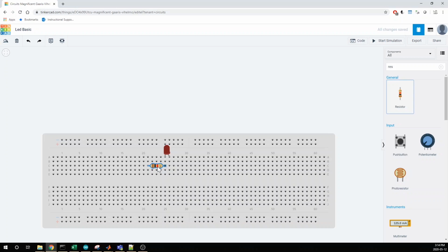But I'm just going to follow along with the standard where you put the resistor at the bottom or the lower potential of the LED. So now I click it, this is where I want it to go, and you'll notice it's no longer following me. And now a new dialog box comes up, and this one is actually fairly important. So it has name, which is fine. I don't care too much about the name, but I do care about the resistance.